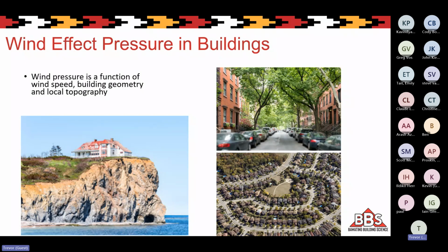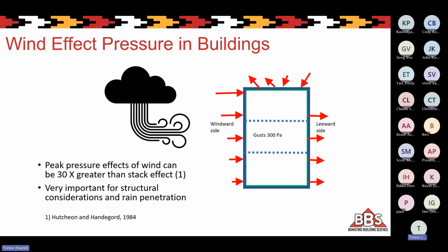Is it out on its own, being exposed directly to the wind? Are there wind tunnels created by tall buildings in the area? When we talk about wind pressure, the peak pressures we're talking about can be really high, up to 300 pascals of wind pressure that we could see in peaks. But these peaks are really important